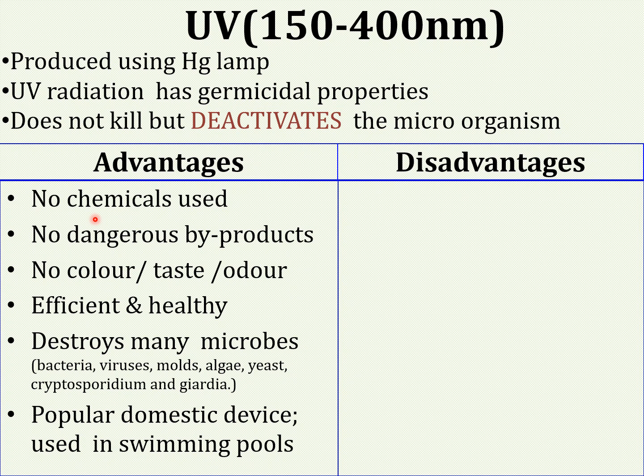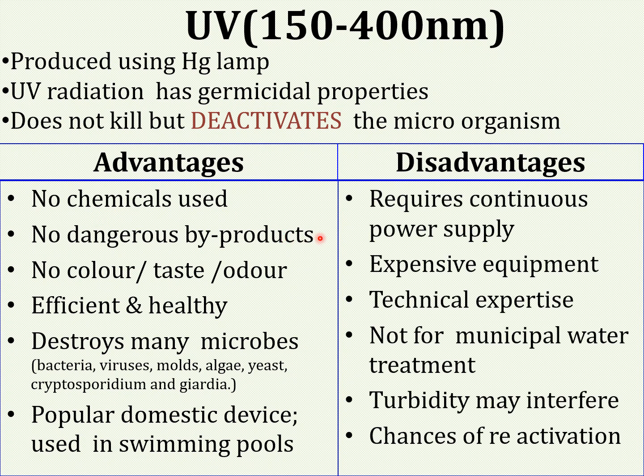But coming to disadvantages, the biggest disadvantage is that it is an expensive process. It requires technical expertise and also power supply. And for all these reasons, this cannot be used for municipal water treatment. And also, since light is used, turbidity may create a problem, and chances of reinfection are also there.